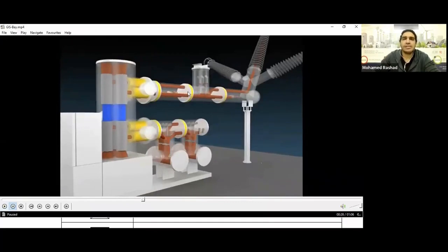It means that if this is a compartment, then this is called a gas tight spacer, meaning the SF6 gas is trapped inside this compartment, creating insulation between this compartment and that compartment, and this compartment and that compartment. This compartment is considered isolated so that the gas inside it is not connected to the gas in the next compartment, nor the previous compartment, nor the first compartment.